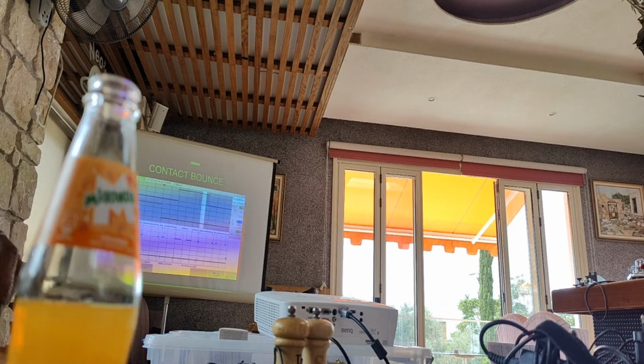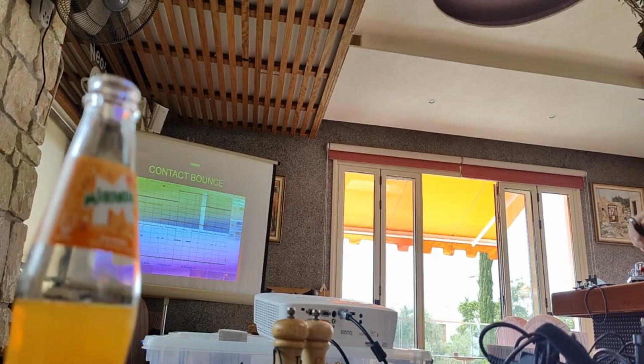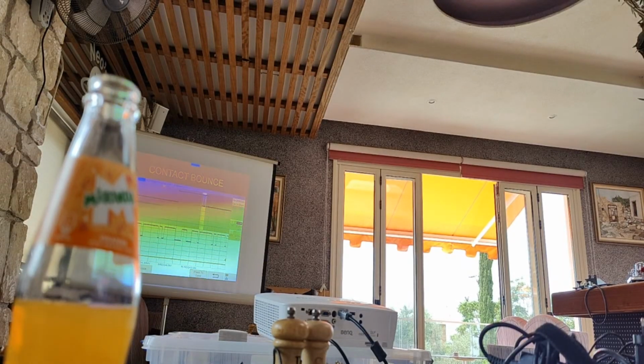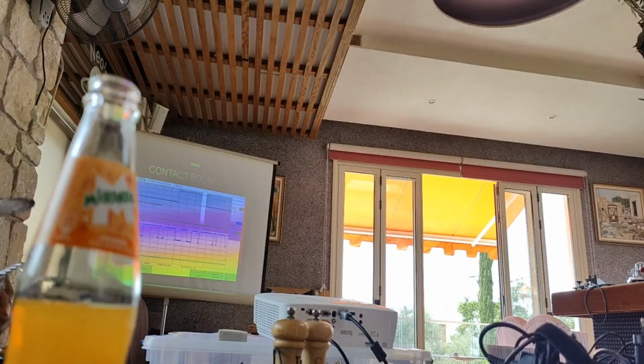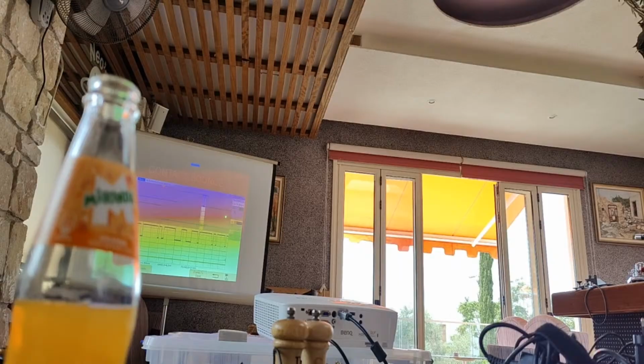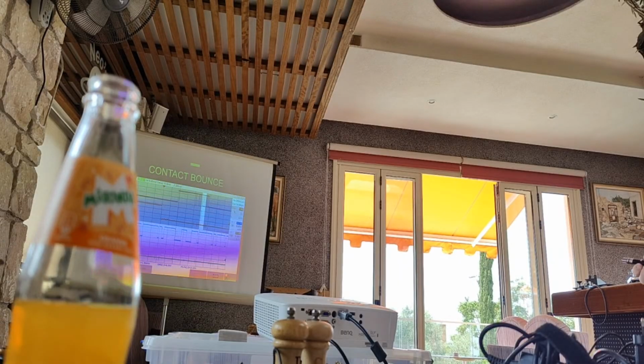This is contact bounce. And I'm afraid that some paddle keys suffer from contact bounce. So if you don't put it in and you find you need it, you'll start sending rubbish. So it's best to put it in, even if you don't need it, it won't do any harm. But it does affect the timing gates. Timing becomes critical for this. So, contact bounce. Oh dear.